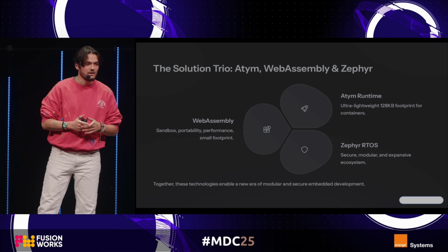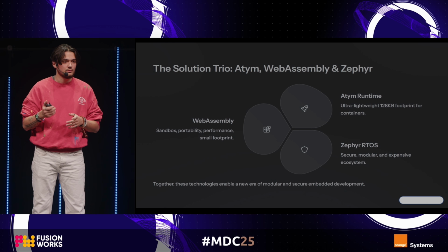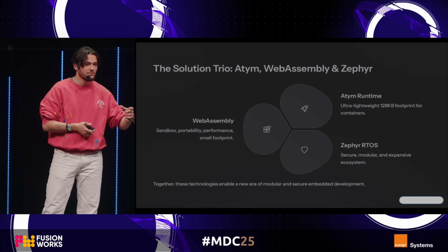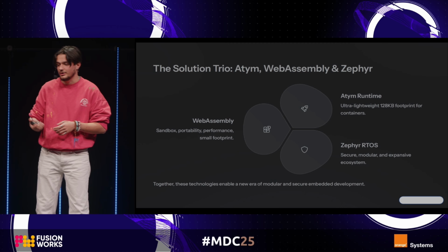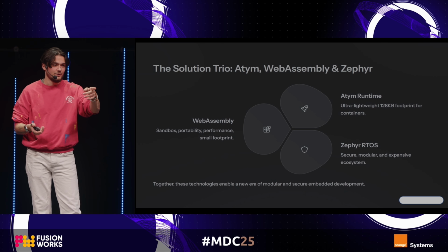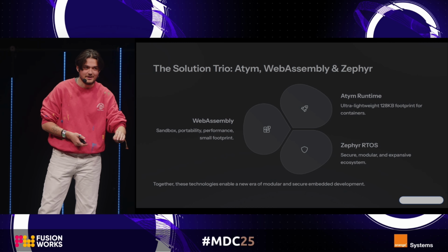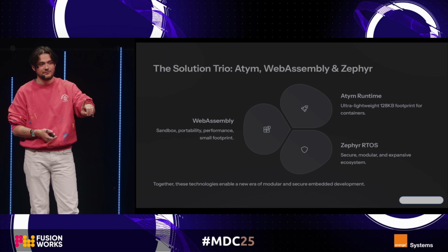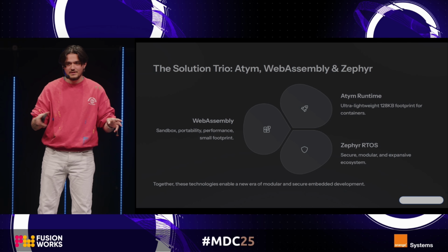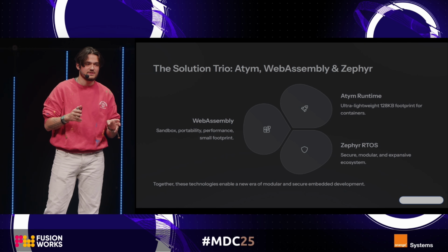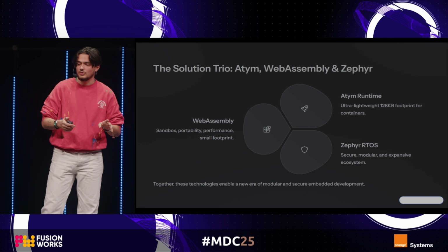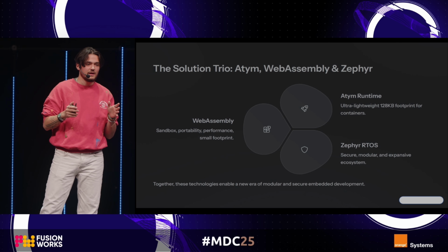We tried to create a runtime in C language so that we can just deploy a WebAssembly application to an ESP32 with 72 kilobytes of memory. So, has anybody heard of Zephyr RTOS? If you are an embedded engineer, check it out, because you really can change one config and compile the same program for different chip architectures and different chips, even from different vendors. I was shocked when I saw this. So, taking these three together, we created